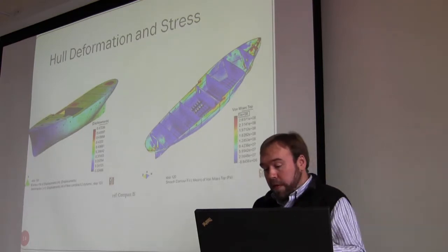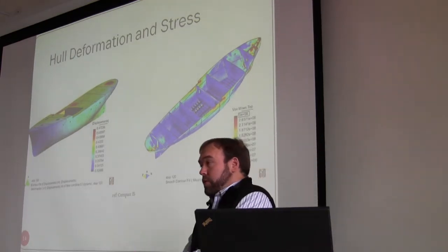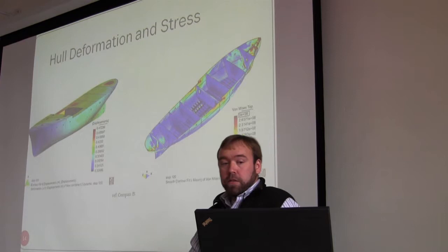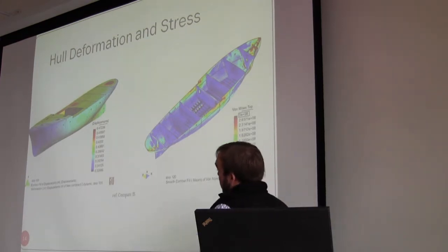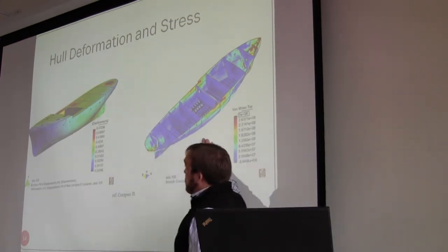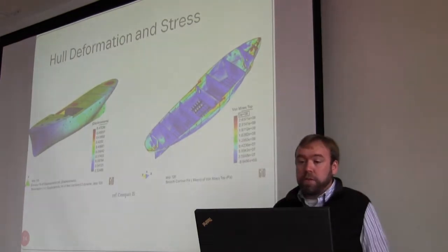So then, taking that information, going straight over to the structural model for RAM series, you can get deformation throughout the ship, as well as the stresses. In this case, we see stresses for all of the shell plating and the interior structure. Okay. So it's a nice package. It is readily available, a readily easy process to go from the FSI problem to the structural problem.